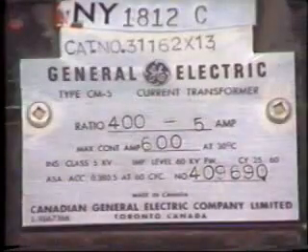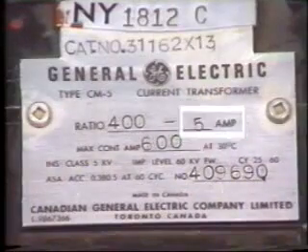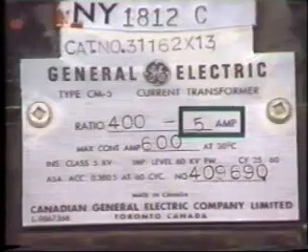To achieve this, more flux is needed, and therefore more exciting current is required from the primary. As a result, distortion increases and accuracy of the transformer is reduced. In sum, then, as the burden increases, the overall accuracy of a CT decreases. Remember, rated current on the secondary is normally 5 amps. We need to remember this when interpreting the standard classifications.